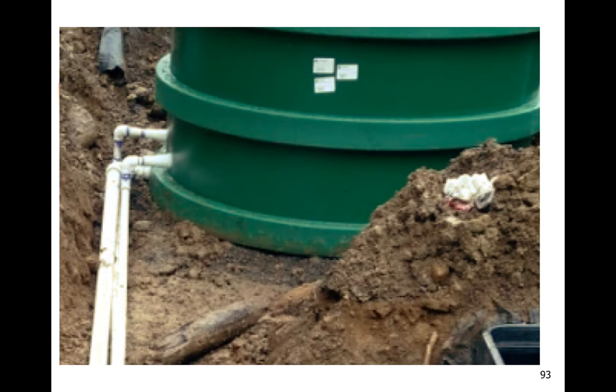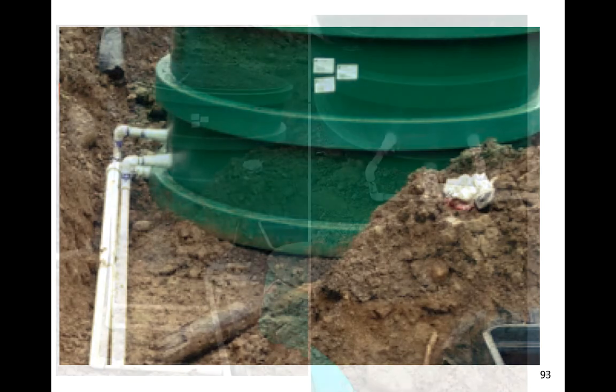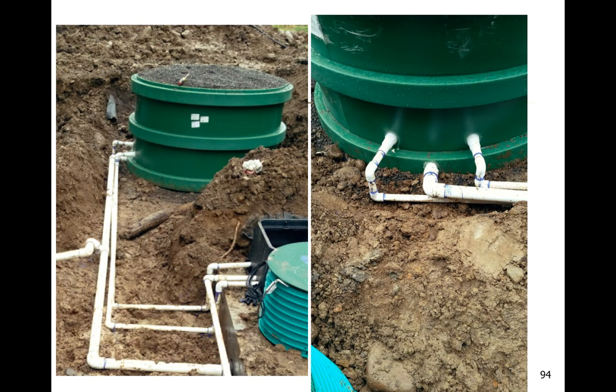So if you rotate the basin 90 degrees toward the direction that you want that under drain to come, put an elbow on there, and then that way you won't have any tension on that fitting, and you'll have the right angle coming out of the tank. From the other angles, here's what it looks like.